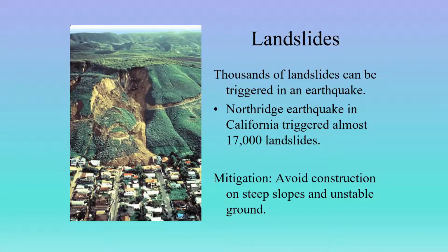Mitigation, then: avoid construction on steep slopes and unstable ground, right? And look at your geology. What are you building on? If it's a series of former landslide deposits, it might not be the best place, right?